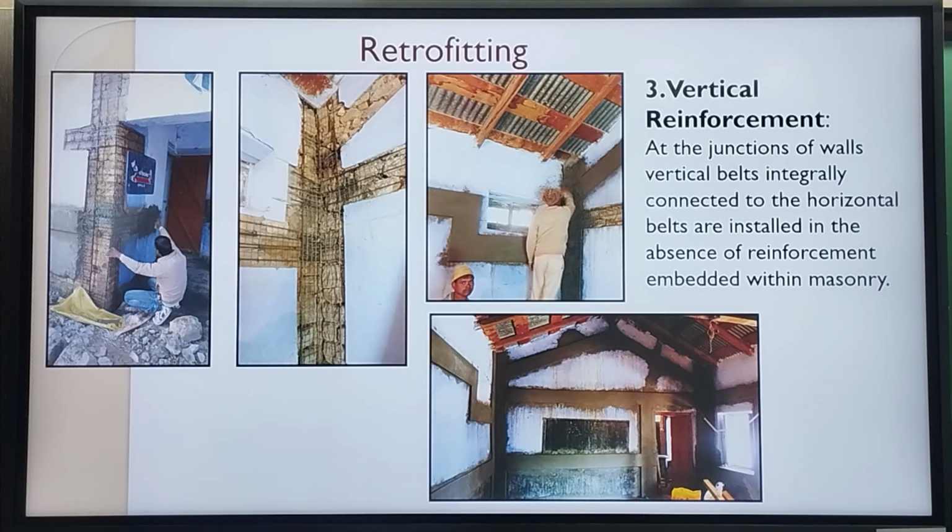Also, when you have a situation like this, this often happens in buildings when you have a ventilator. Typically, that is just at the lintel or slightly above the lintel, right in the middle of the alignment of the belt. So either you can bring it down or you can take it up, depending on which will work, where you are able to accommodate the belt.